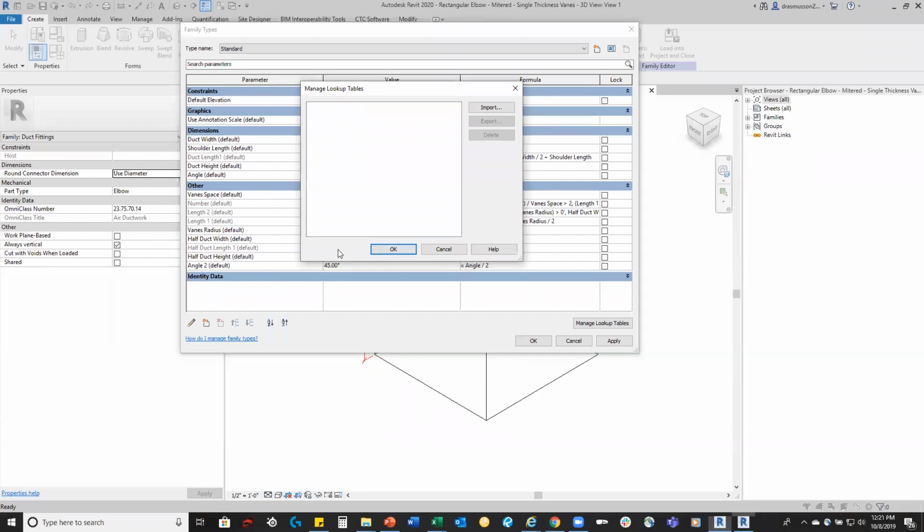The way that I've always played with the coefficients, everyone, is to set my own. If I'm running a static pressure calc in Revit and want it to be super accurate, I will go through the system and set my own coefficients per the fittings that I have in there.